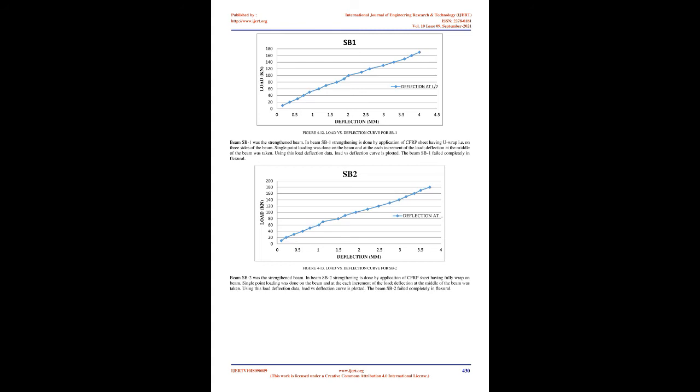Experimental setup. The testing procedure for all the specimens will be the same. First, the beams will be cured for a period of 28 days, then the surface will be cleaned with the help of sandpaper for clear visibility of cracks. The single point loading arrangement will be used for testing of beams.